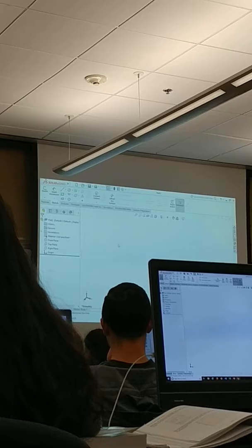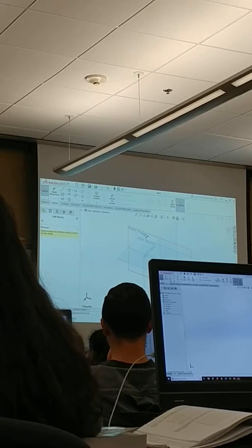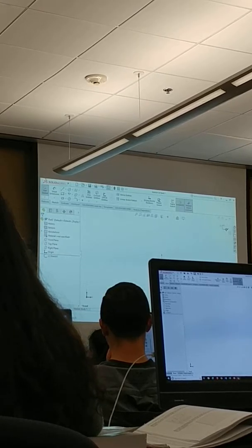Okay. This is my starting screen. But I can't sketch yet. I have to pick a plane. It doesn't know what I want to do. So I hit sketch. I pick a plane. Now I'm in sketch view. And the reason I know that is because these showed up over here.